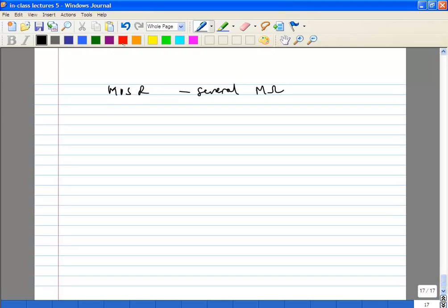And the other thing to remember is flicker noise. Remember that ideally your resistors are supposed to have only thermal noise. But many of these resistors, well, not many of them, some of them could potentially show flicker noise. Because flicker noise inherently happens at interfaces between different materials, and when you rely on silicon based resistors, you naturally expect it won't be as high as MOSFETs or even bipolars, but there are some special cases where you could see flicker noise.